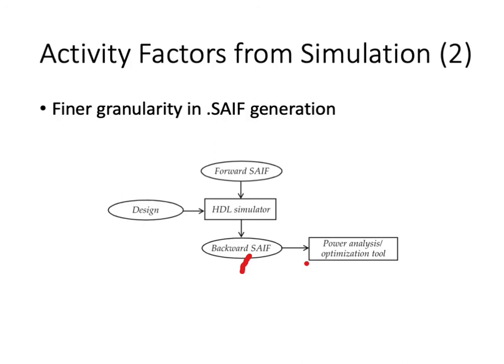But you also have the possibility of specifying other SAIF files, called the forward SAIF files, that are input to the HDL simulator before the simulation is run.